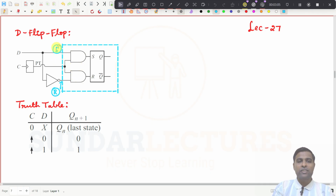So now what we are doing here is putting a NOT gate for these two inputs. What happens now? For example, if I give D is equal to 0, so I am making it D now. This 0 will go here. Let us assume that a constant clock pulse is available. So if it is 0, then S is equal to 0.